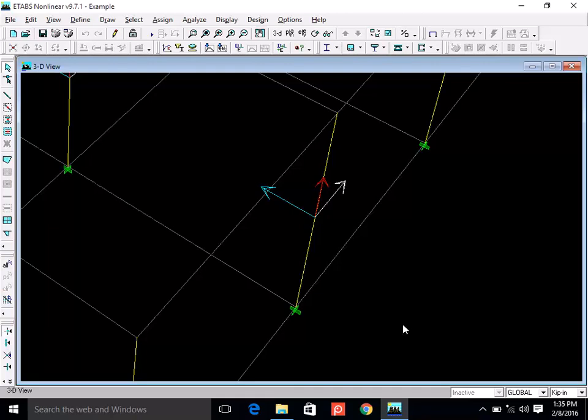But how about this axis? Look, this column has like 15 feet tributary area on one side, but on the other side, outside, there is no load. So all the load is on this side, and when you calculate the resultant, that would lie somewhere here. So that is an eccentricity, and this column will definitely have moment about this axis. So this column has moment about this axis, but no significant moment about the other axis. It means this is a uniaxial column.